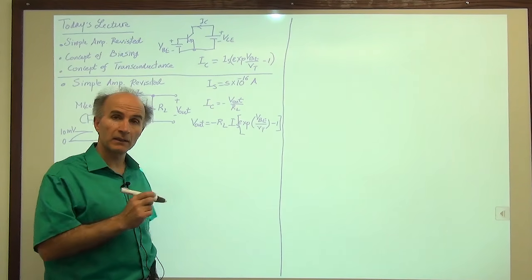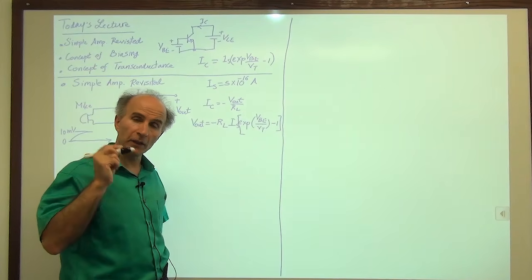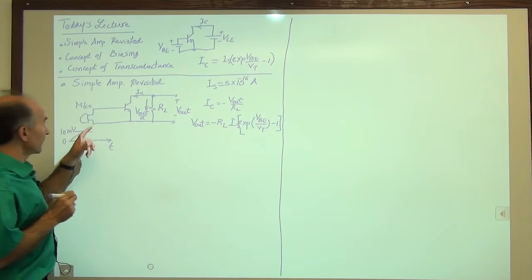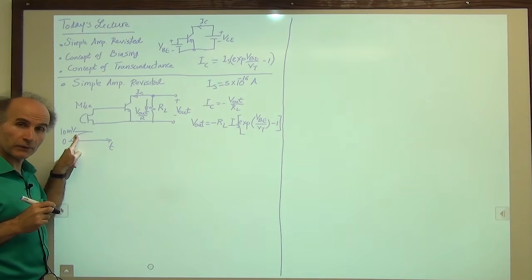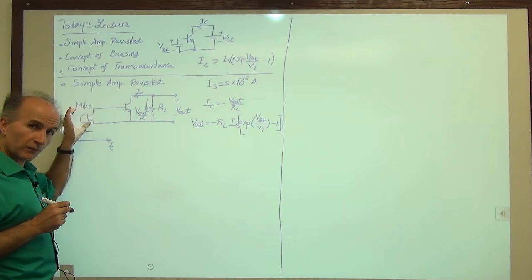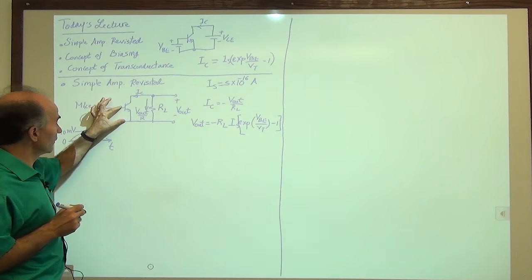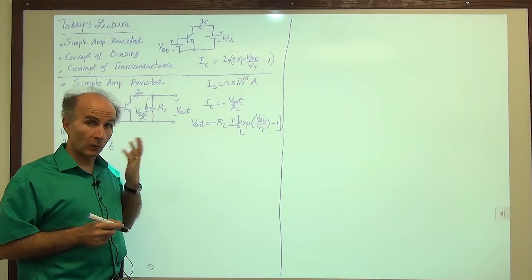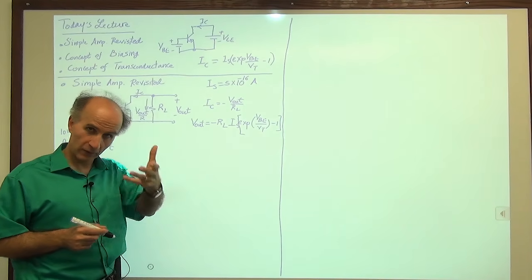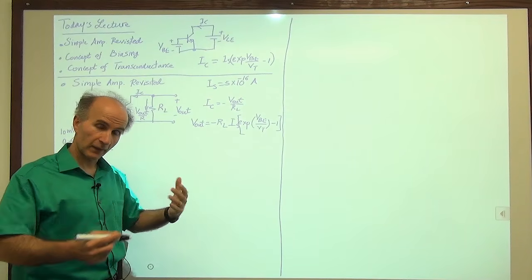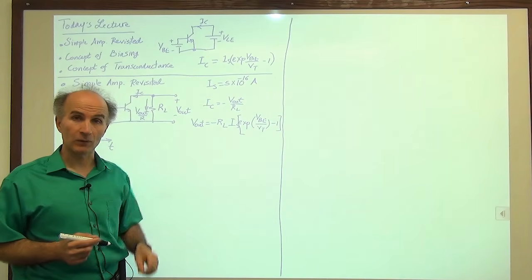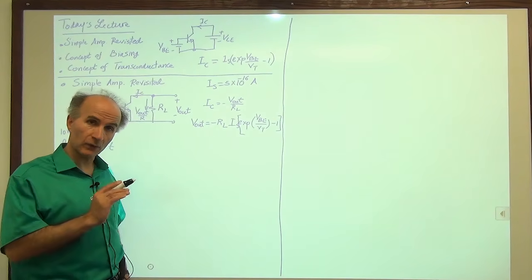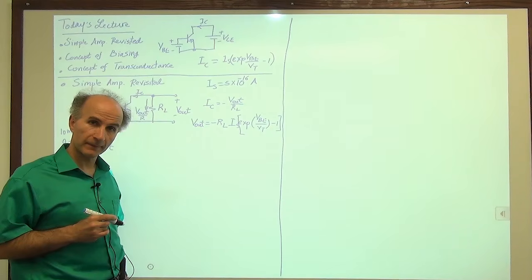All right, so right here, you should hear an alarm in your head, because I am saying that the base emitter voltage is 10 millivolts. Right? The microphone signal goes from 0 to 10 millivolts. So the base emitter voltage is 10 millivolts. Isn't that awfully small? From what we know, the base emitter voltage, which is a diode, is about 700 to 800 millivolts. So we are giving it only 10 millivolts. So something will probably go wrong. But that's okay. Let's move forward and see what happens.